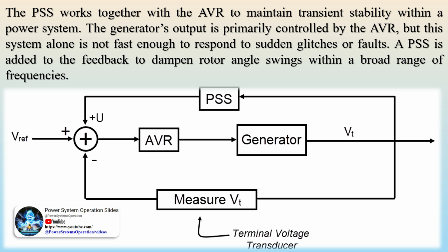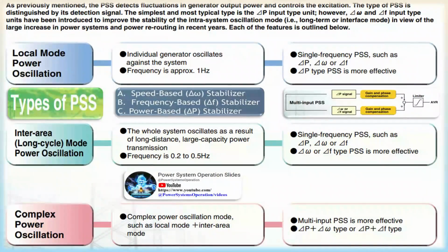There are 3 types of oscillations observed in power systems. Inter-unit oscillations typically involve 2 or more synchronous machines at a power plant or nearby power plants swinging against each other, with frequencies ranging between 1.5 Hz to 3 Hz. Local mode oscillations generally involve 1 or more synchronous machines at a power station swinging together against a comparatively large power system or load center, with oscillation frequencies ranging from 0.7 Hz to 2 Hz. Inter-area oscillations involve combinations of many machines on one part of the power system swinging against machines on another part, with frequencies normally less than 0.5 Hz.